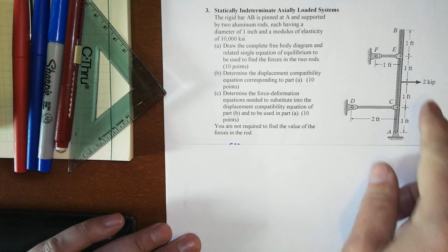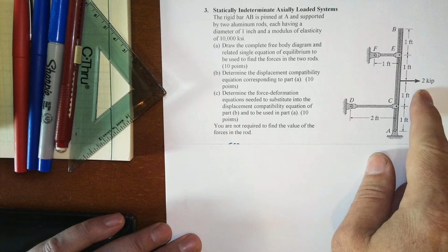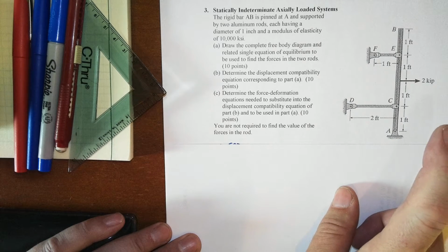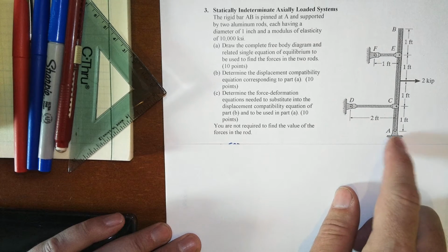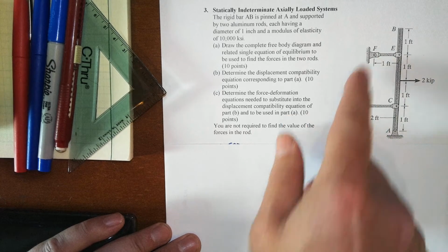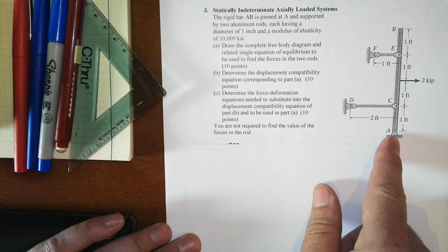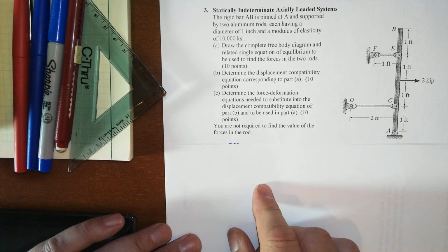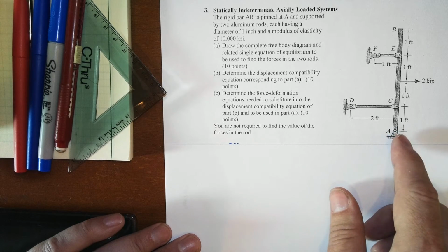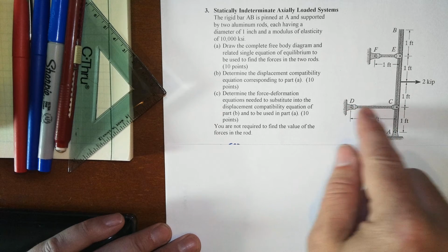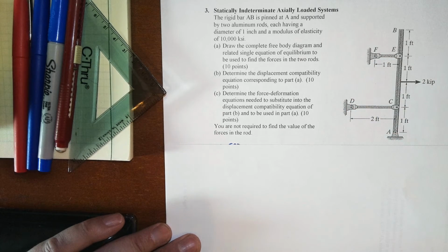And we have a 2,000 pound force that's applied up here at the mid-height of this thing. The system is pinned down here at A to the rest of the world. It's pinned at D and it's pinned at F. These are locations where there are no translations. There are potentially rotations because there's a pin there. There's nothing from the external part of the world to prevent that. So note, no applied loads to members CD and EF; they are just pin connected members.